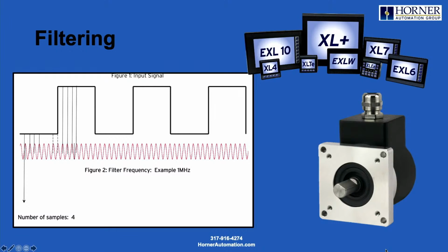Well, then we're probably, as a rule of thumb, going to want to set up a sampling frequency or a filtering frequency that's about 4 times that. So let's say 40K. And then the other thing we configure, and that's where these little lines come in, those little lines on the left there are basically looking at each sample.